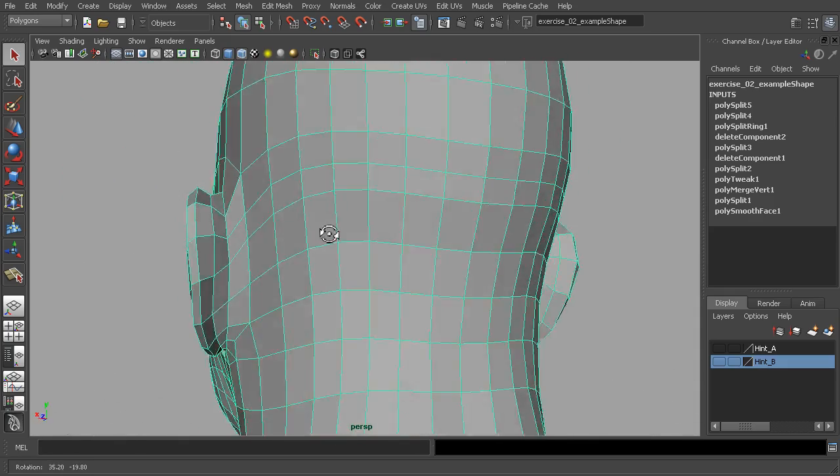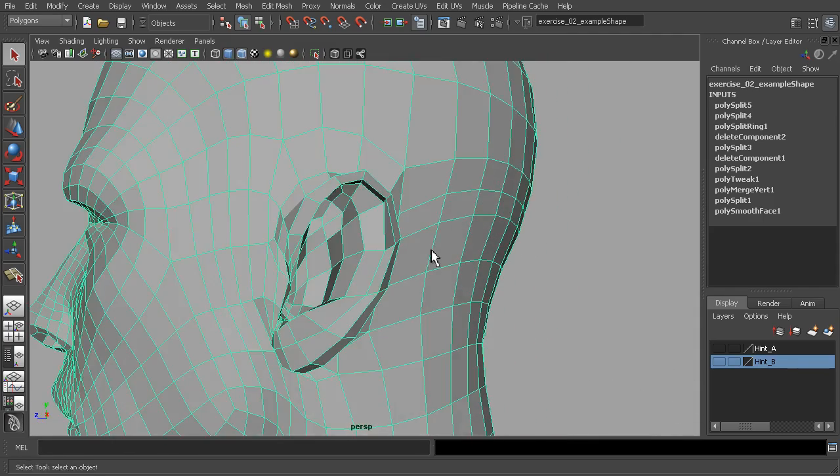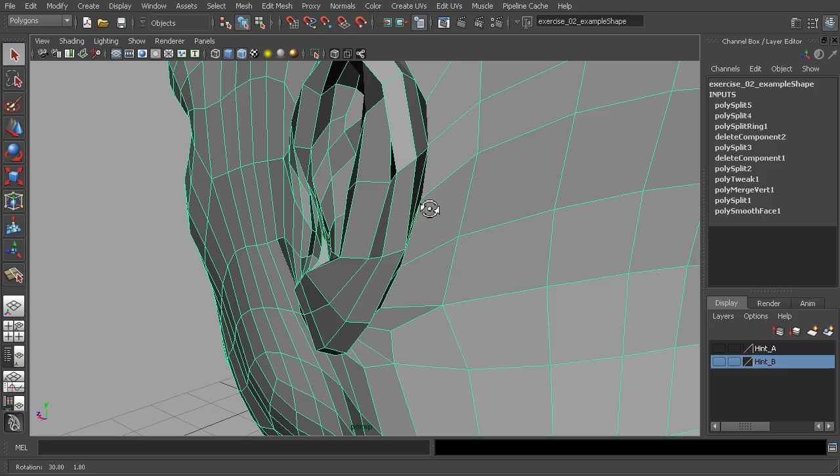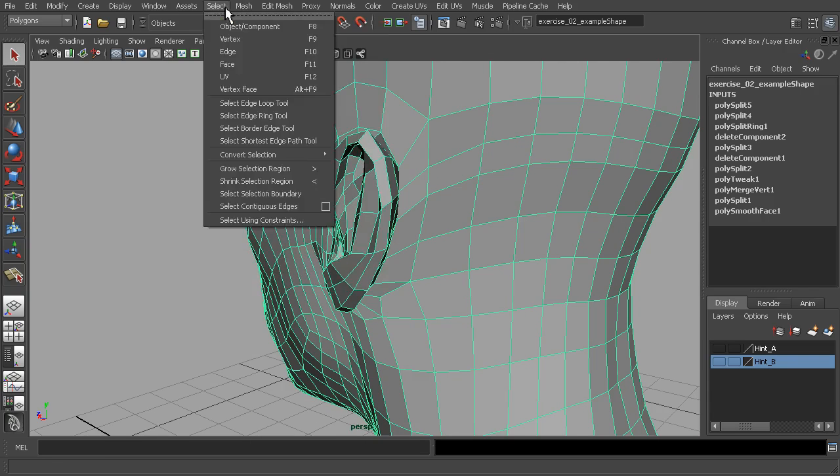Okay, so that enables you to get rid of that one. So you can again terminate on one of the edges to make that into a quad, or you can take one of those triangular edges, pull it away from one of the points, and extend it logically across the surface, just like that. All right, so let's go ahead and check this again.